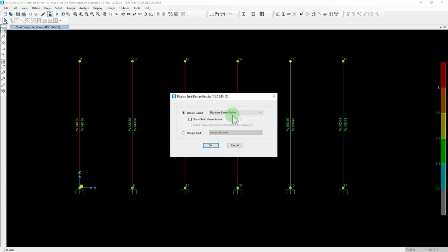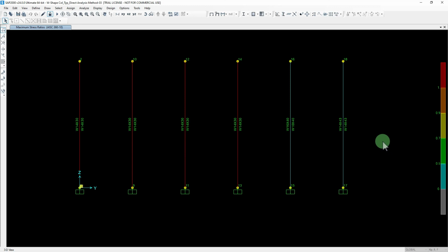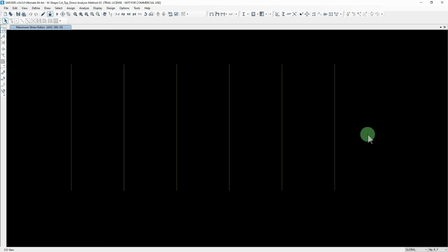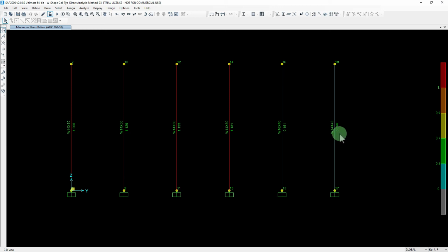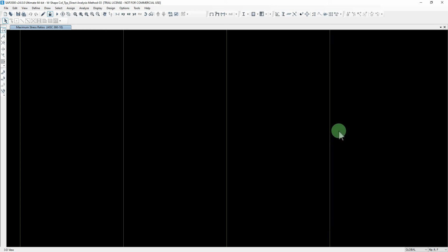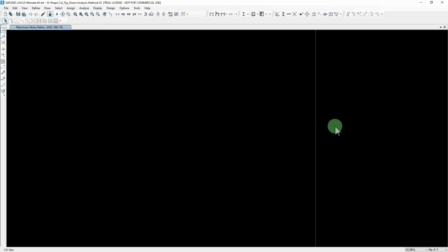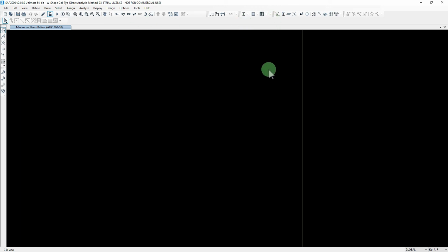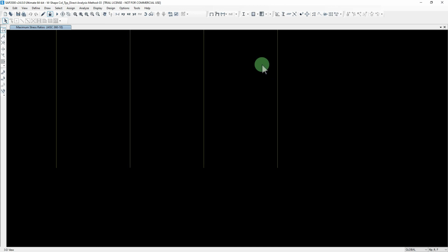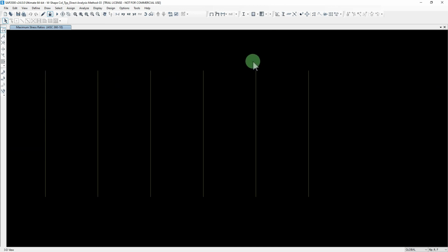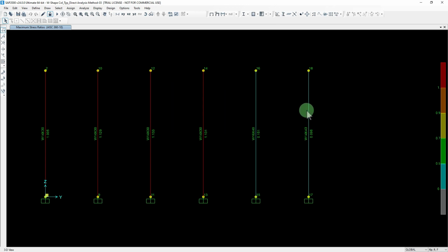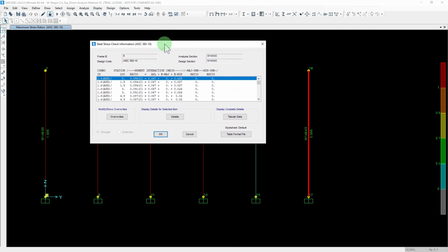When you take a look at our design ratios, everything else is the same. You'll see the one that was the 14 by 43 has a design ratio of 0.09, so about 10%, instead of 13% like Risa was telling us. Reason why that is because SAP 2000, at least as far as I know, does not do an accurate check on the axial capacity. So this is something that I need to write to SAP about, basically.